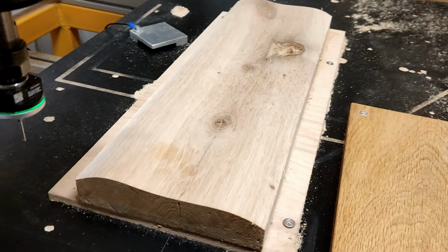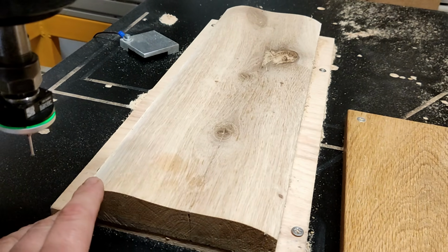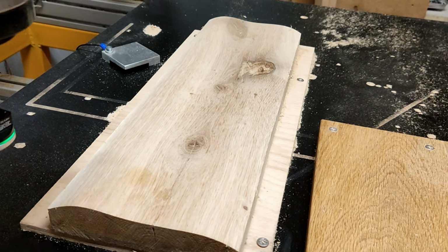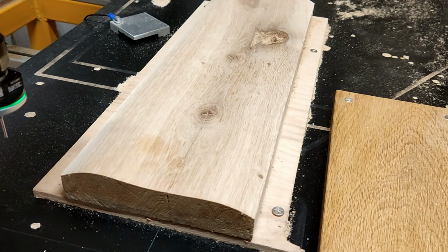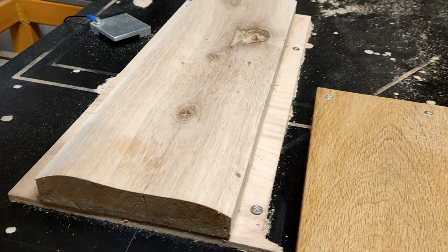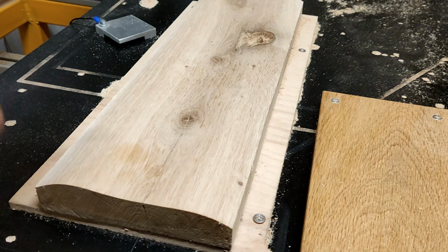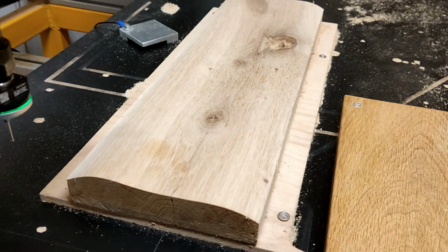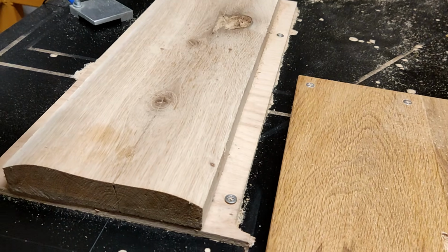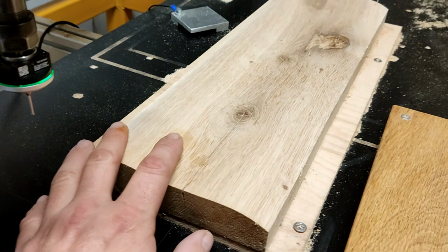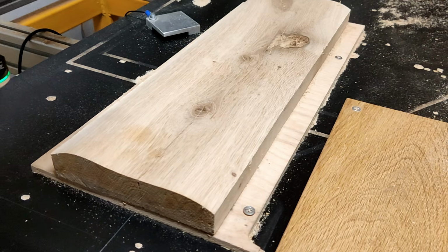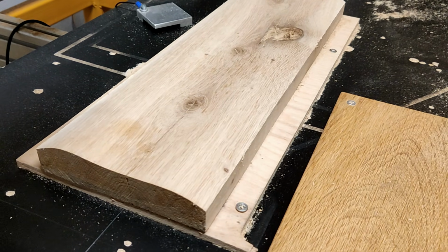Let me start by telling you a little bit about the piece of material that I have here on the table. It's a piece of oak and it is really wavy. I did this using a 3D surface operation because I wanted it to be exaggerated, so it is easier to see in the video what I'm talking about. So let me quickly set up an engrave operation and I will engrave on this surface the logo of my channel, the logo of Open Source CNC, using a 90 degrees V-bit.